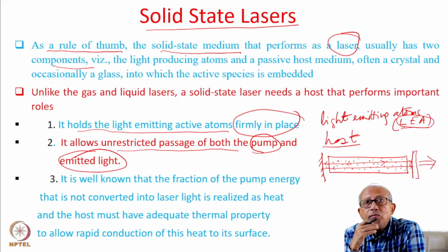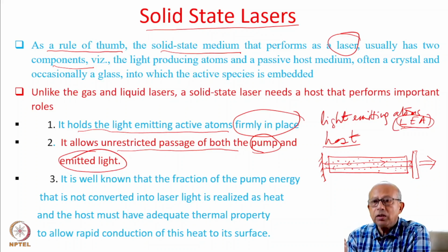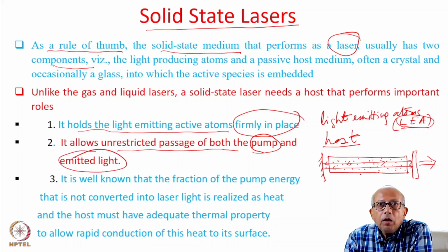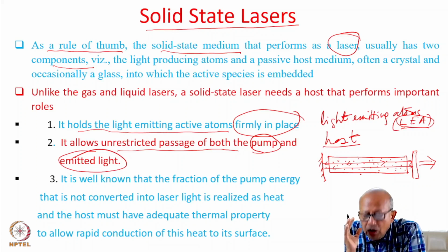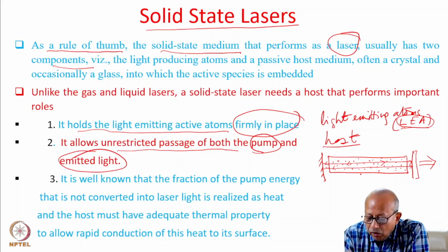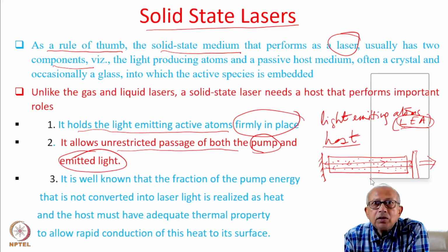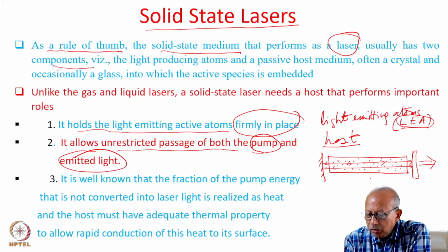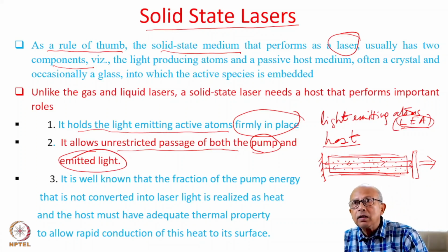And also there is another important function of this host material. We now know very well that the fraction of the pump energy that is not converted into laser light is eventually realized as heat, and the host therefore must have adequate thermal property to rapidly conduct this heat onto the surface. So these are the three most important roles that the host material plays, and that makes the performance of a solid state laser.